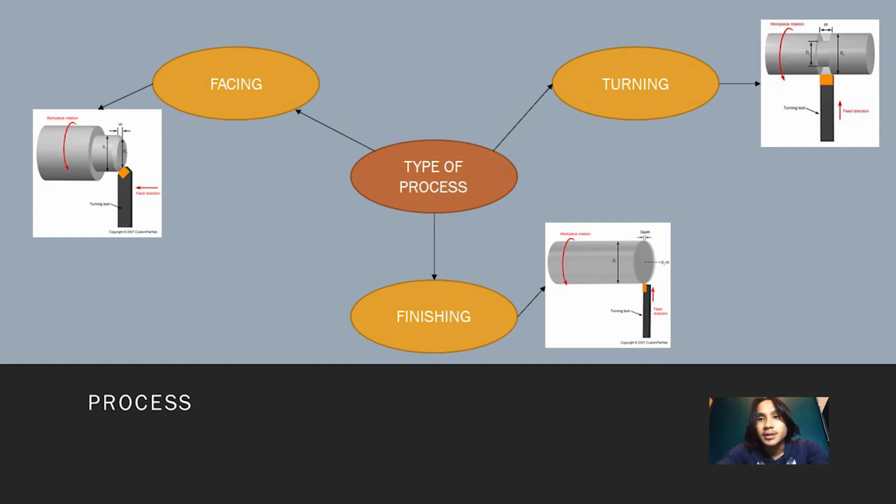The next process is the turning operation, or turning process. It is a method of removing metal from the outside diameter of a revolving cylindrical workpiece. Turning is also used to reduce the diameter of the workpiece, usually to a specific size, and to give the metal a smooth surface. The workpiece is frequently turned in such a way that neighboring pieces have various diameters.